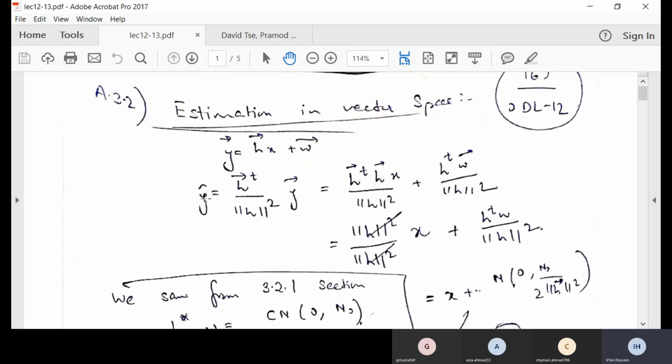So we know once you need to estimate x, we have the coherent channel modeling. You multiply the received signal with ht over h, but here we deliberately multiply not with ht over h mod, but ht over h mod square. So it is a little bit different from what we have done in the early part of chapter 3.